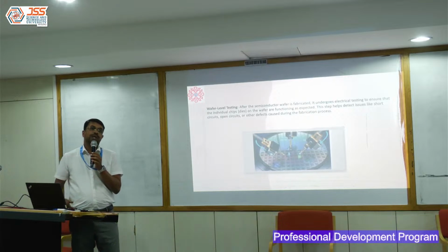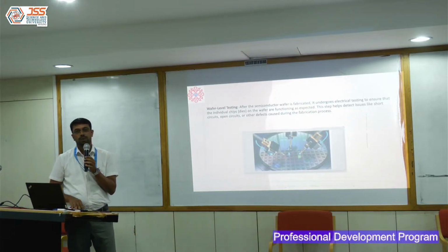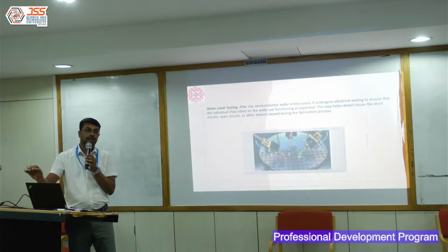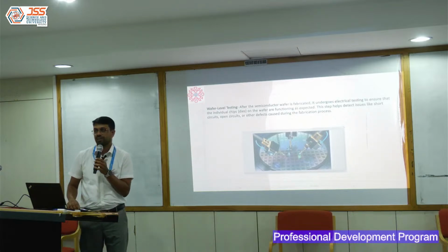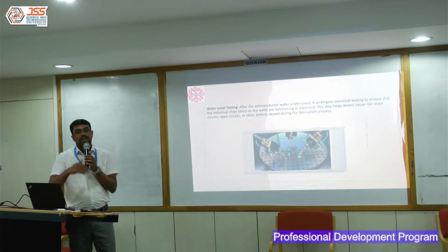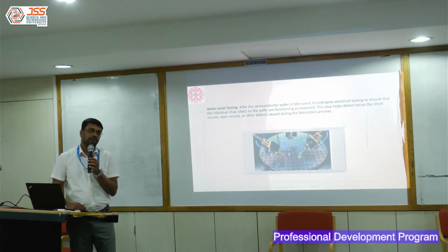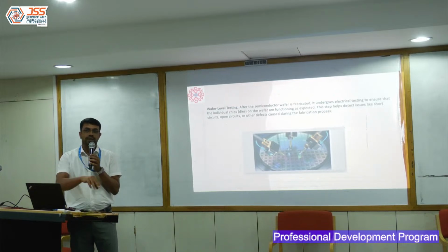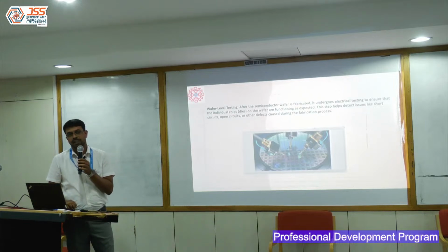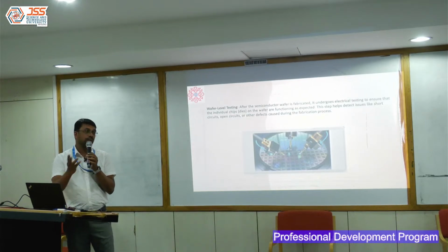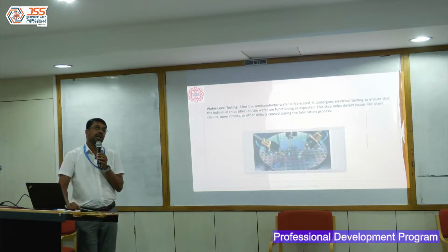So what we do is we categorize certain tests which are very critical, and which we think that any component, if I want to call it a pass, it has to pass this basic test. Then there are a few other optional patterns. Depending on the end product and the application, we will decide whether to try those patterns. Should we make it part of the test program or leave it? Based on that, we juggle between quality and yield.